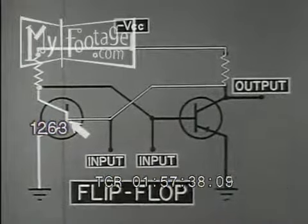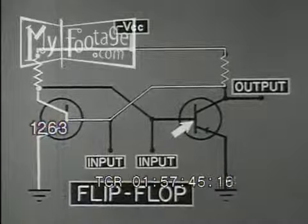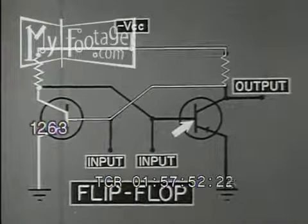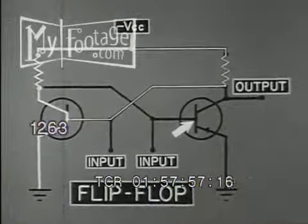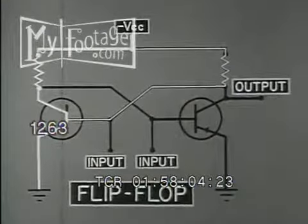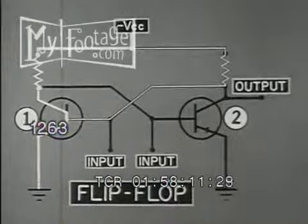The first transistor's collector voltage is 0 because the collector is saturated. Applied through the cross connection, this 0 voltage keeps the second transistor's base at ground potential. With no potential between its emitter and base, the second transistor cannot pass current. Switch 1 will deliver an output indefinitely until a negative input is applied to switch 2.